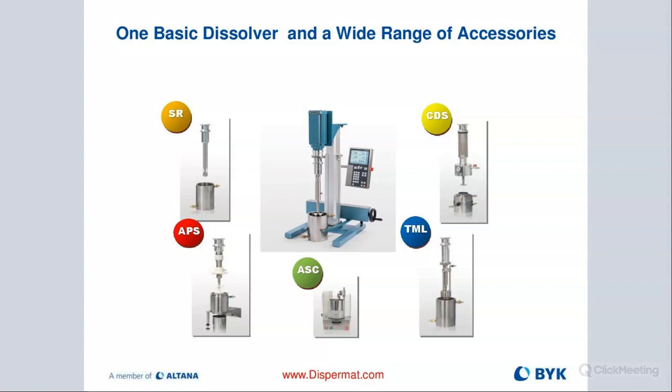On the bottom left, you can see that APS system, which is that vertical media mill or pot mill that we can attach. It's more for the laboratory scale. It's not really for manufacturing because you would need a tremendous amount of beads in this type of setup where you can have 100% bead loading to your product loading. So it's more for lab scale and not for manufacturing.